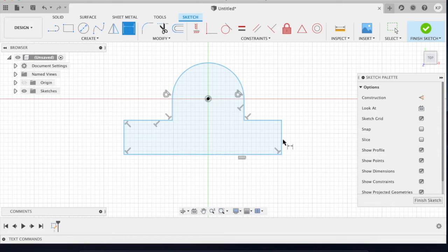And when you dimension an object's width, you could grab this line, but we want to make sure that we say from this line to this line, it's a certain width. This helps lock everything in, and you'll see that things will start going from blue lines to black lines. And we're going to choose 5 inches. So now we have a length.